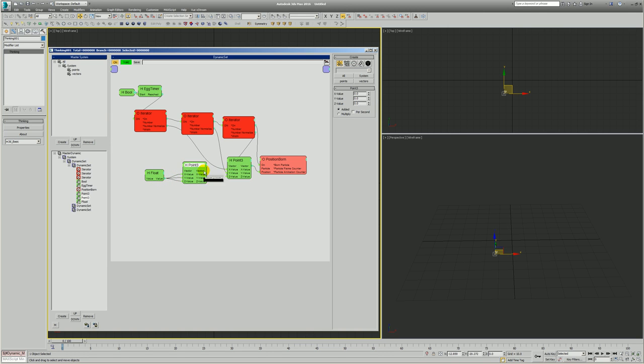Interesting thing about this is, if I want my overall units to be 100, basically, if we're going to use the multiply on point 3, we have to set that to 1. So this is going to come in as 100 on all 3 axes, and that vector gets multiplied against the normalized values, which will be from 0 to 1, so 0 to 100.